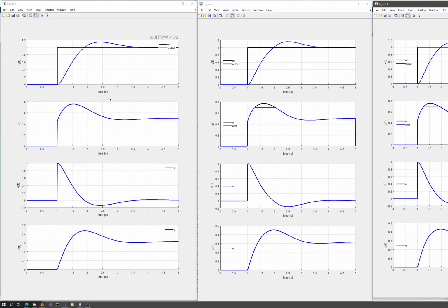And you can also see that your time specifications are very crucial in terms of control and real-world applications, because you are the one who is deciding the settling time, rise time, and overshoot properties. Most probably the system or the application will tell you what the overshoot should be. For example, if you have a chemical process, if you're heating a certain substance or chemical compound, then most probably overshoot should be 0, and it should be restricted so that it will never ever overshoot. So the application will tell you. If you have a mechanical system, let's say a robot manipulator, and you should not hit any boundary, then there should be no overshoot. So having no overshoot is most probably a thing that you will take into account.